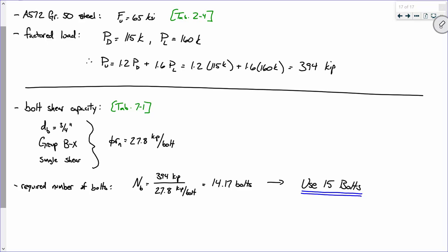Hey, now hold on. Say that again. There you go. In a practical design scenario, that's probably a better answer. Just go with a different bolt, or go with threads included versus excluded, although we don't have that option here. But maybe using a bigger bolt and collapsing that down into a more manageable connection. Do you see what I mean? You got to design a connection that makes sense. Is everybody okay with that? This is an important discussion to have.